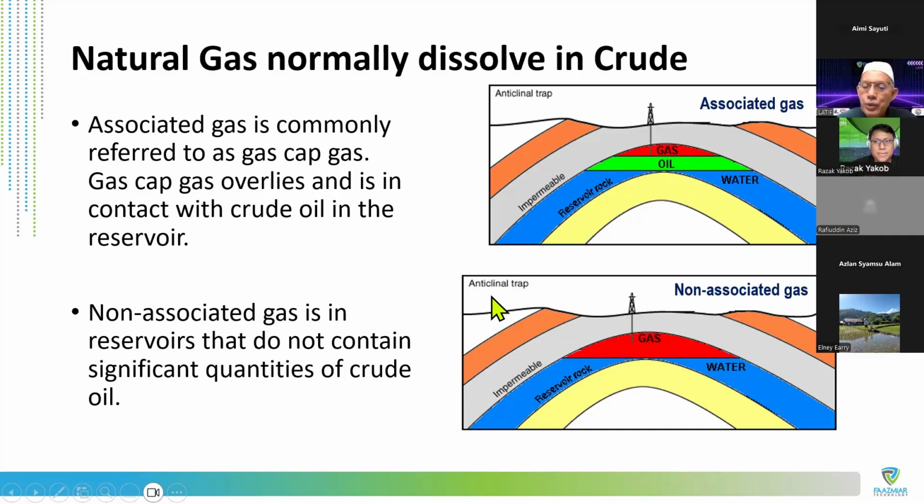Okay. So some other areas have a different trap, and sometimes you have all the gas itself and the water is pushing up. So the water system here actually provides additional energy to push the gas. When we produce the oil, what happens? We deplete the pressure because we are sucking, creating a vacuum effect in the reservoir.